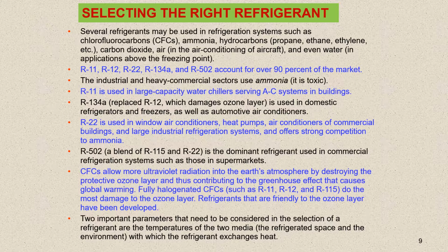When designing a refrigeration system, there are several refrigerants from which to choose, such as chlorofluorocarbons like CFCs, hydrofluorocarbons, HFCs, hydrochlorofluorocarbons or HCFCs, ammonia, hydrocarbons like propane, ethane, ethylene, etc., carbon dioxide or air in the air conditioning of aircraft, and even water in applications above freezing point.